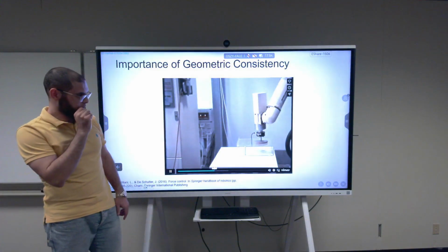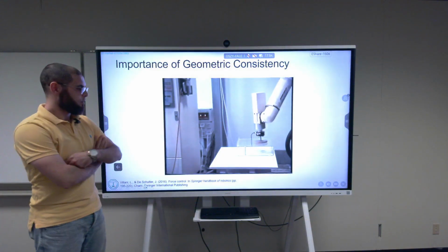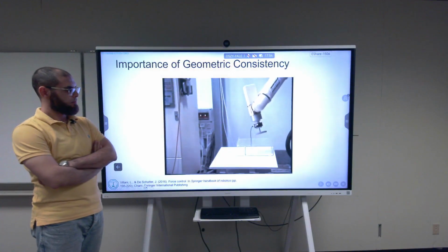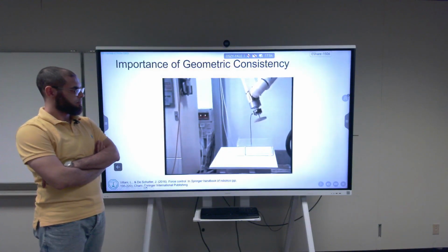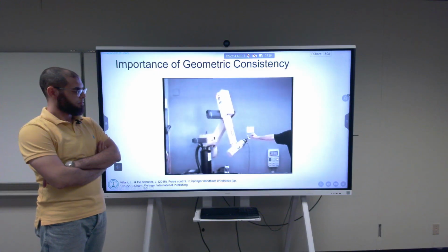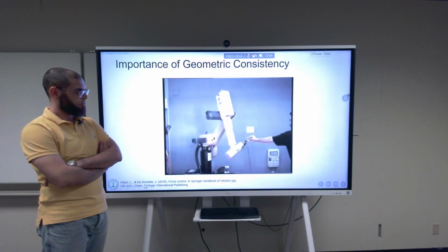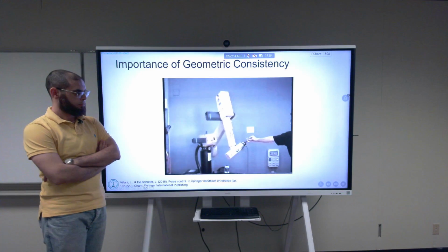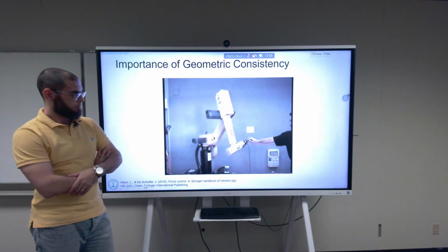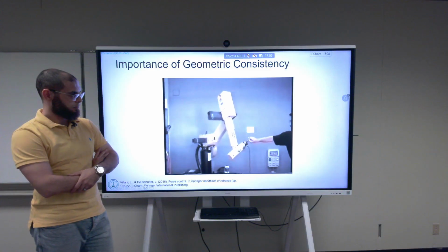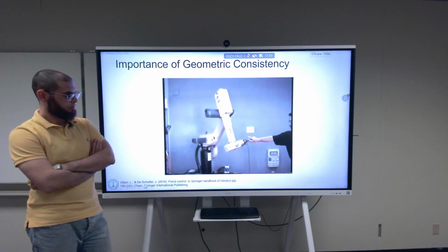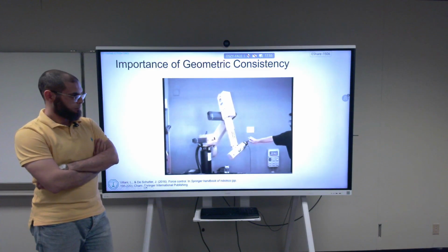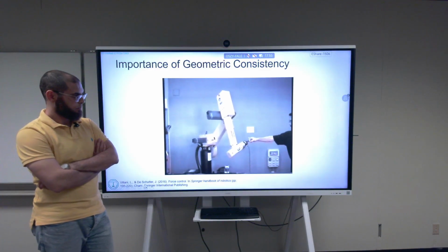When the end effector tool comes in contact with the surface, a compliant motion is obtained so as to accommodate the interaction force and moment. When performing a 6-degree of freedom interaction task, a spatial impedance has to be considered, involving an end effector position displacement as well as an end effector orientation displacement.